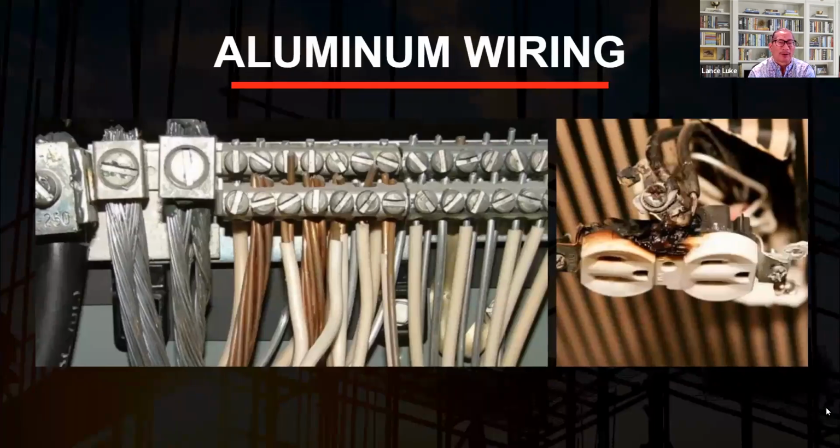Now, I put aluminum wiring in the defective building material category only because the aluminum wire is different from copper. It has different characteristics. Copper is a better conductor of electricity. Aluminum, the size of the wire has to be one size larger than the copper in order to carry the electrical. And what happened with these branch wiring? In branch wiring, I'm talking about your wires to your electrical outlets and your light switches. Those are 15 and 20 amp circuits.